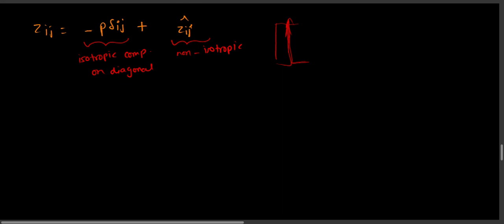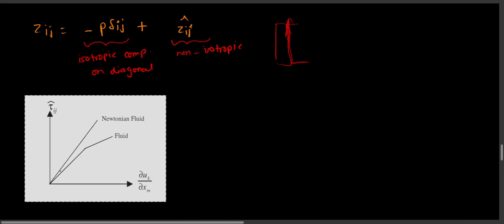And I'll just copy one experimental graph. Okay, just a second, I'll copy the experimental graph here, and here we have it. So of course scientists carried out certain experiments, because who is a scientist without a lab? And we found out that for a Newtonian fluid, the dynamic stresses, you can call them dynamic stresses because they are acting when two particles are moving relative to each other, are related to the velocity gradients.